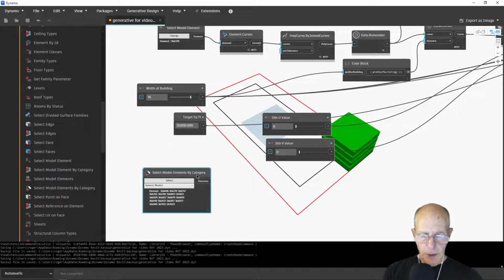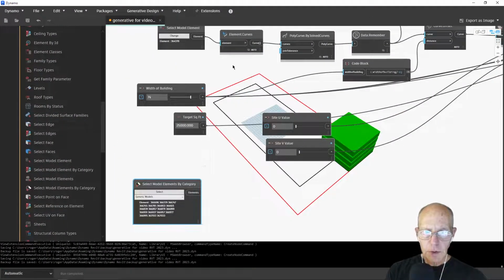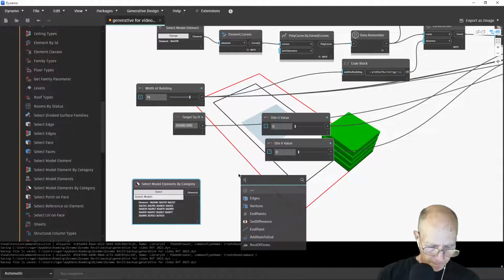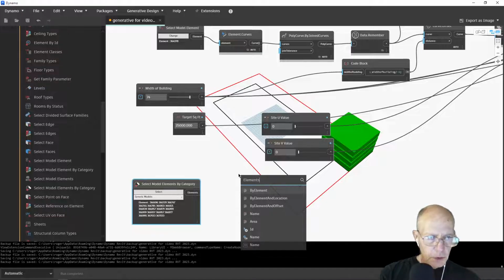And now that we have those in again, I can stretch this out full screen and we can continue with bringing that geometry in. So just as we did before, we have elements, but they haven't been defined as anything that we can see inside of Dynamo. And so I want to make that visualization possible now. And we're going to do that by using, instead of elements curve, element geometry. So there's probably a selector Element.Geometry.